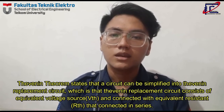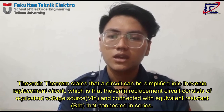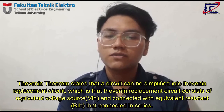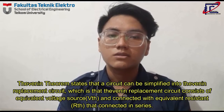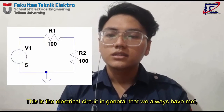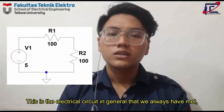Thevenin theorem states that a circuit can be simplified into a Thevenin replacement circuit, which consists of an equivalent voltage source connected in series with an equivalent resistance. This is the electrical circuit in general that we always have met.